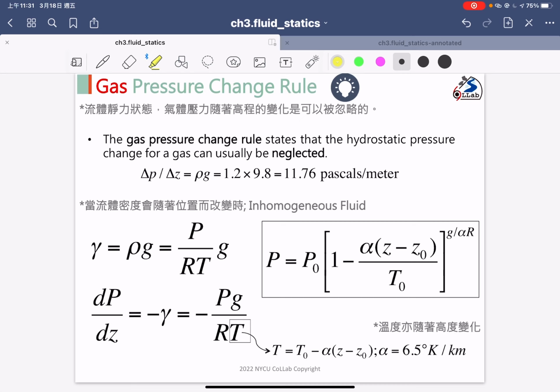But the previous slides always focused on liquid, and we know the fluid can also be gas, right? So this slide shows an example focused on gas, and how it differs. The significant difference for gas is that the gamma is totally different. If we consider the gas to be air, we know the air density is 1.2 kilograms per cubic meter, but for water it is 1,000.